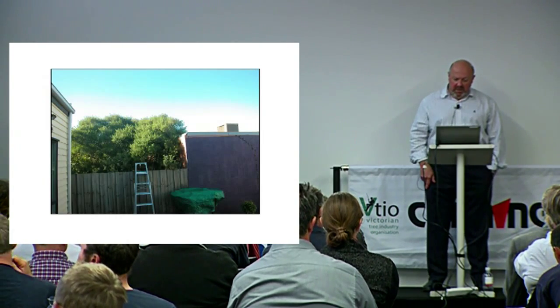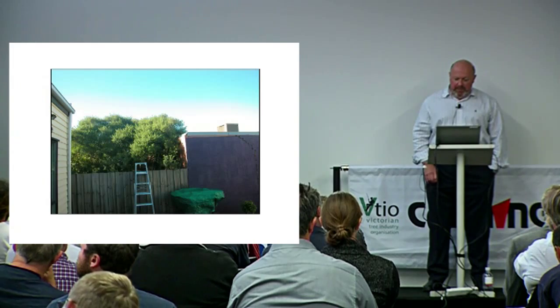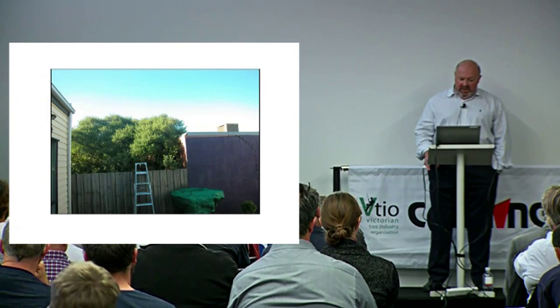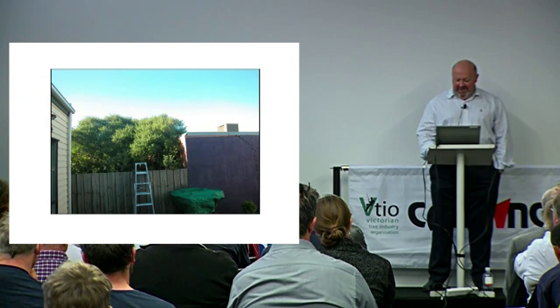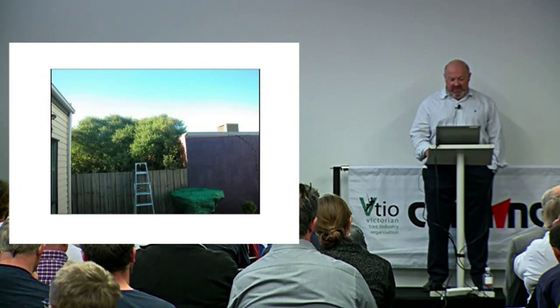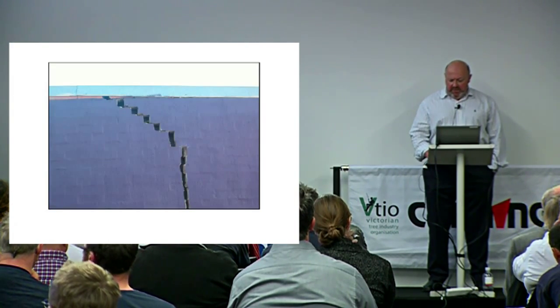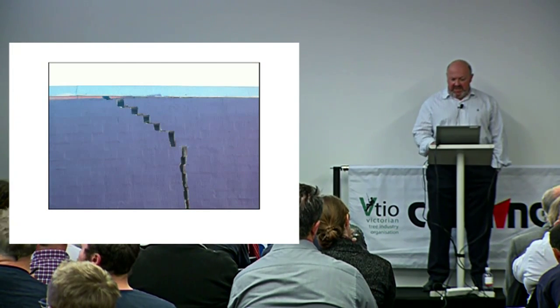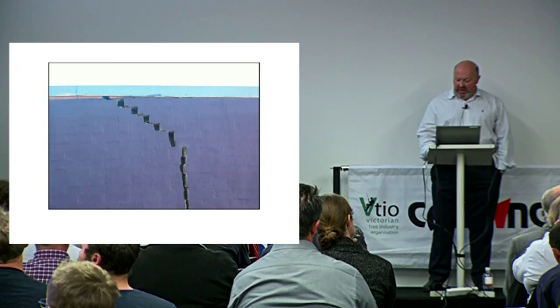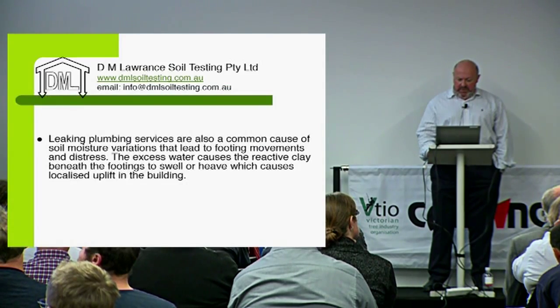This is a case we're asked to look at by another geotechnical company who are getting into trouble. But that's just another indication. I think that if it close up of the crack, yeah, you can see that's quite a significant crack as well. That's a typical sort of crack pattern when you're getting a drying action underneath one end of a building.